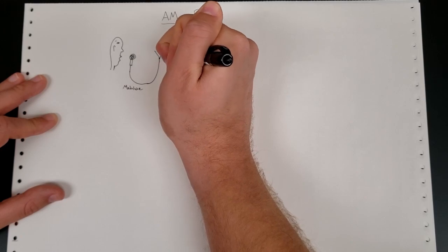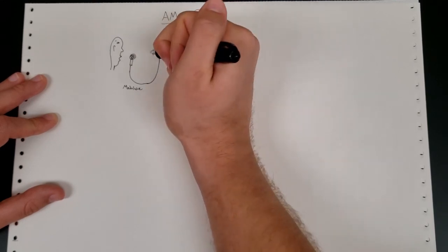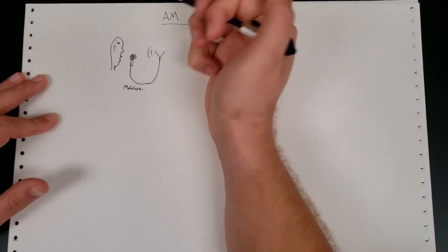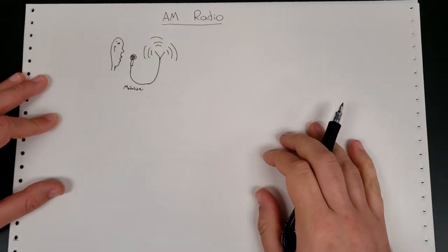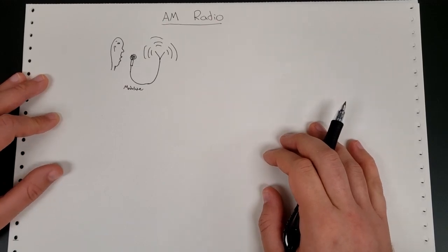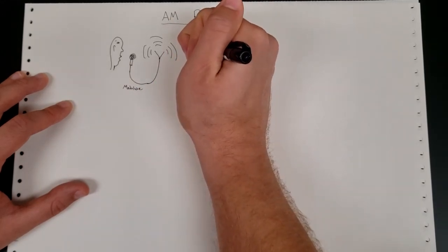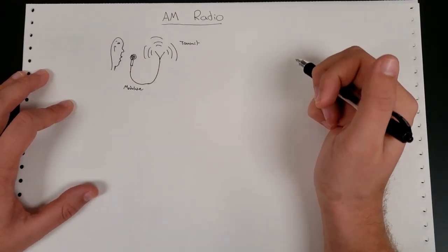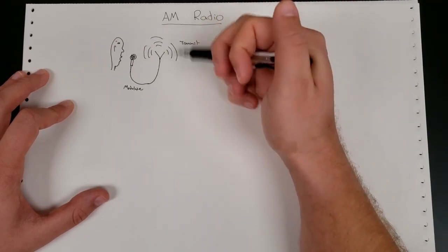Okay. And we'll talk about all of these steps in more detail. This is just your general idea, and then we'll go through and talk about each one in more detail. But we modulate a carrier wave using this small signal produced by you talking into a microphone or wherever your signal is coming from. And then we broadcast that signal, which can then travel much further, on the order of miles versus on the order of meters, right? Whenever we were just talking about sound waves. All right, so we modulate the signal, we then transmit it using an antenna. All right, and then on the other end, some distance away, we have our radio that can now pick up this transmitted signal.